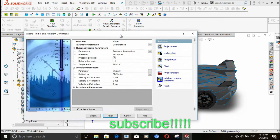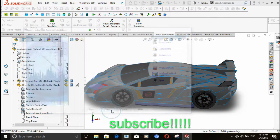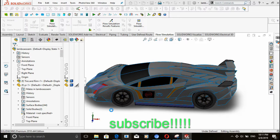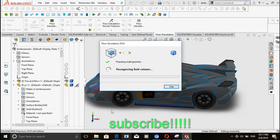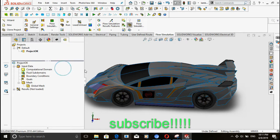Now at this level, this is what we're going to have here. So you just say okay, finish, and you allow it to calculate the volume of the fluid and carry out the necessary parameters, and you continue once this is done. It's going to carry out fluid recognition of the volume. So you're just going to wait for the analysis to be done, and this depends on the speed of your computer. Once this is done, everybody can see the Flow Simulation icon here. I just come here and click on this Flow Simulation icon.